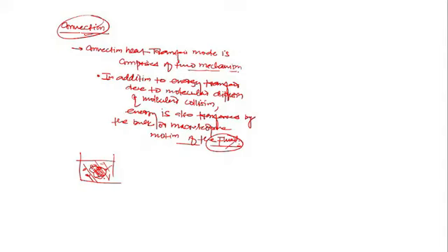So when you place water in a pan, there is no bulk motion, no microscopic motion, no fluid motion, but there is molecular motion. So what I am talking about is convection comprising conduction. Can you say this is a mechanism of conduction? Yes, this is a mechanism of conduction. That's why I told you in the last lecture, convection is nothing but conduction along with bulk motion. In addition to energy transfer via conduction, there is one additional mechanism, that is called bulk motion. So when conduction is added to by bulk motion, that's called convection. Clear?